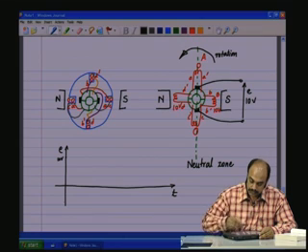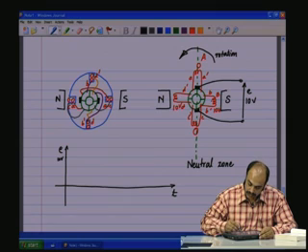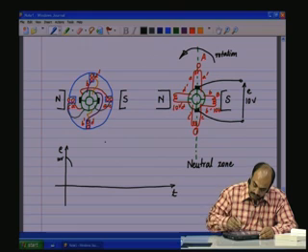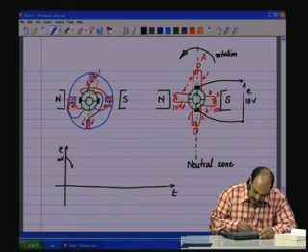Now, what is happening to the voltage across the brush? As it is moving, the voltage across the coil B and coil D is decreasing, and voltage across coil C and coil A are increasing. So, at some point in between, even before it has come to 0, the voltage across coil C would have increased beyond, and the brush would take the sum of the voltages of the coils which comes between these two due to the commutator segments, and it will have a wave shape like that.